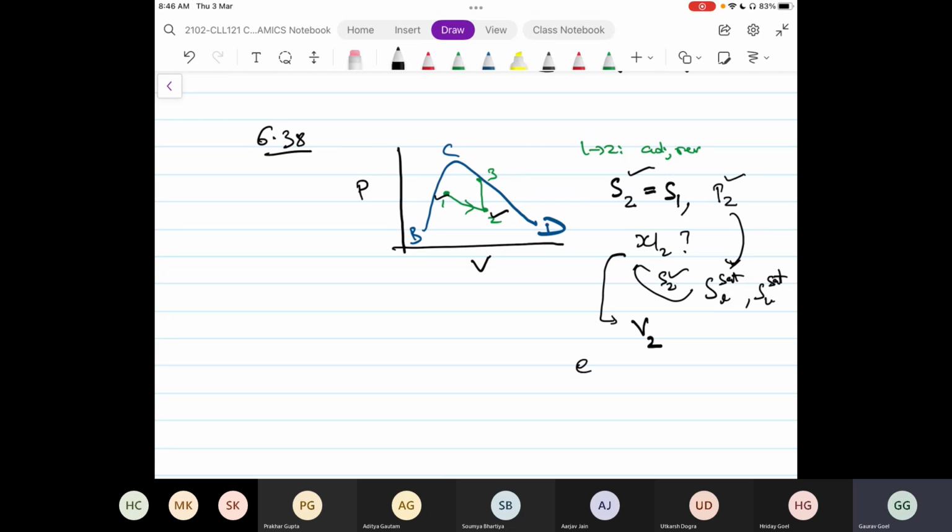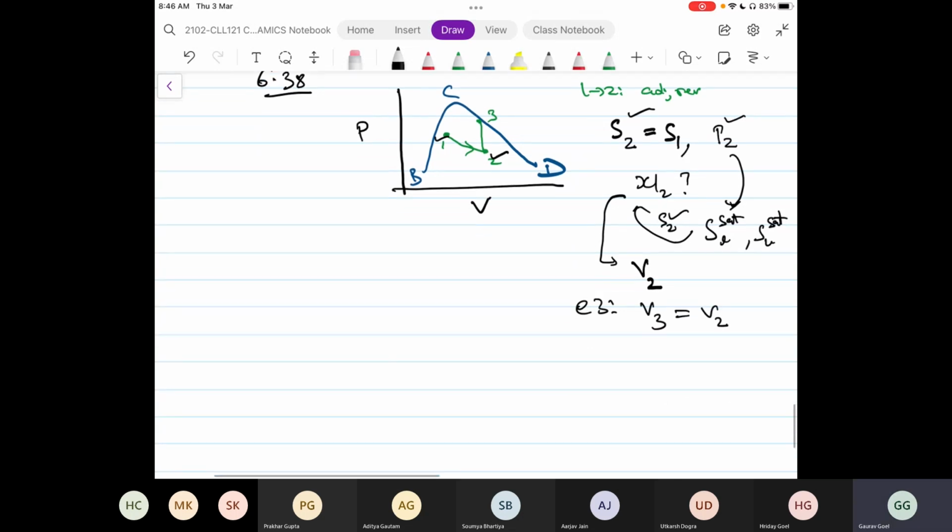All right. Now if you go to state point 3, state point 3 also has become fully specified, because you know V3 will be equal to V2. And for state point 3, they have already said that this is 100% saturated vapor. So that means I know at state point 3, VV sat. And because it's 1 degree of freedom, from here you can calculate pressure, temperature, enthalpy, etc.